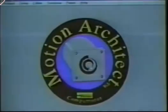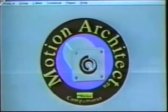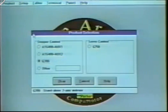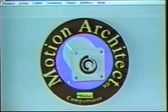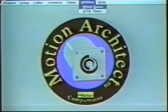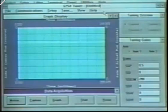We will begin in the main menu of Motion Architect. The product must first be selected. The default is the 6200 and the 6250 servo control must be chosen. That changes our main menu in Motion Architect. The 6250 tuner must be selected under the Utilities menu. This is our main screen.